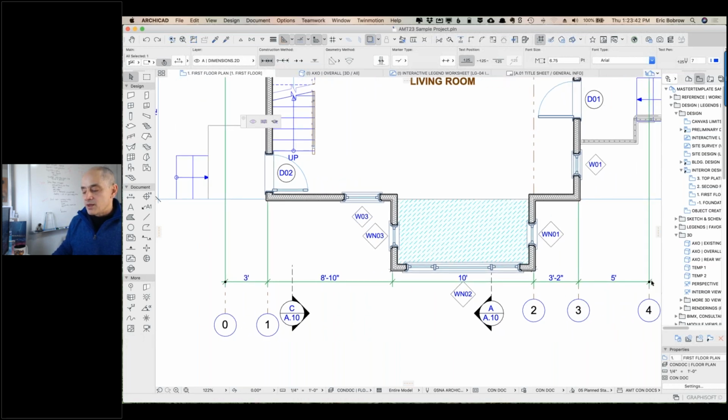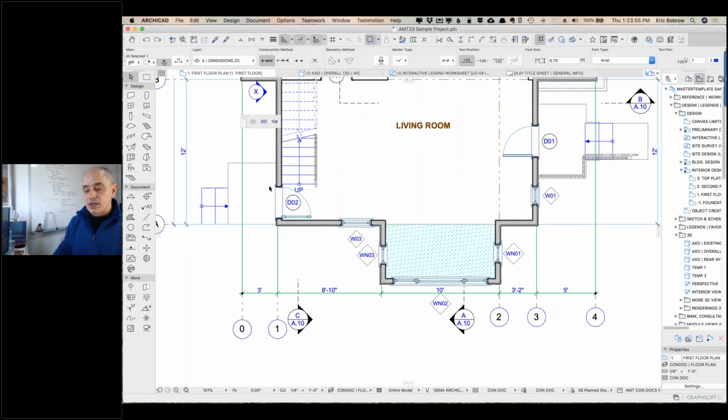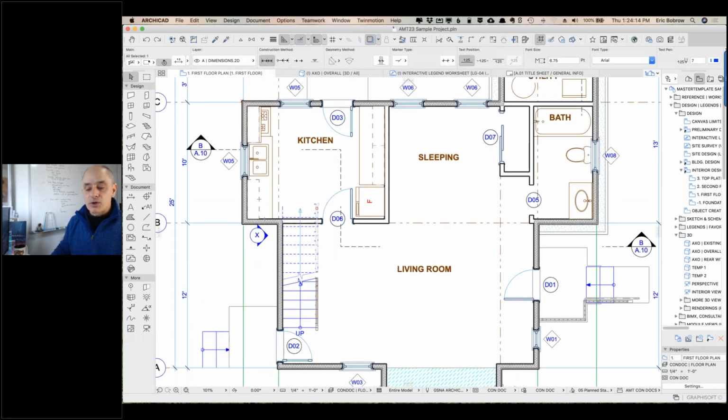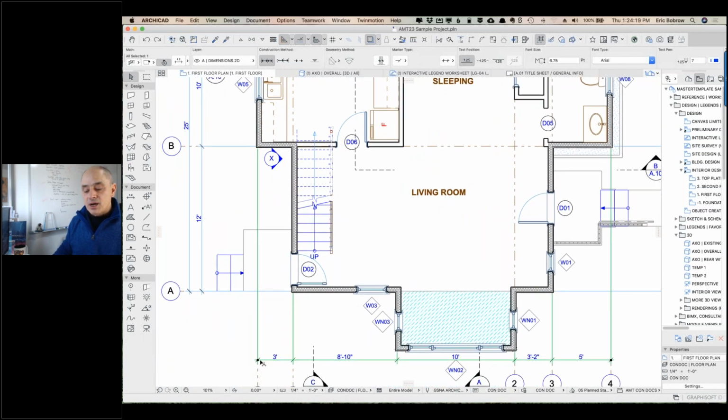I'll just zoom out a little bit. These are highlighted. They are the handles. Now, I can't actually say pull this over to make the reference of the building wider. This would be making the building, instead of 3 feet along this area, some other distance. Why is that? Well, in part because if I were to change this distance here, what is going to move? Is it going to be just this one wall? Is it going to stretch that wall? Is it going to affect the back wall? Is it going to move the cabinets, etc.? So we can't really change it that way.